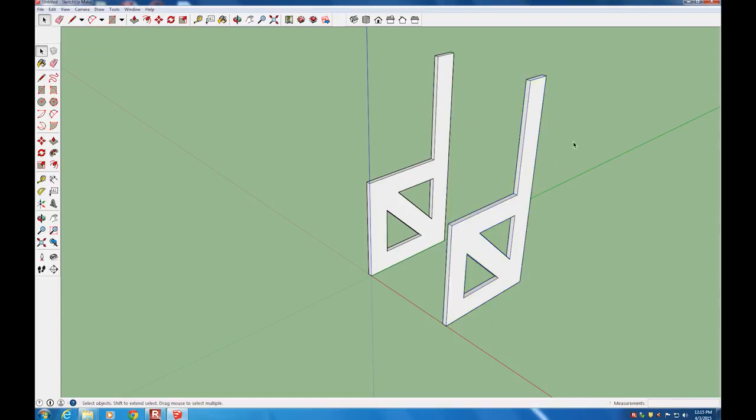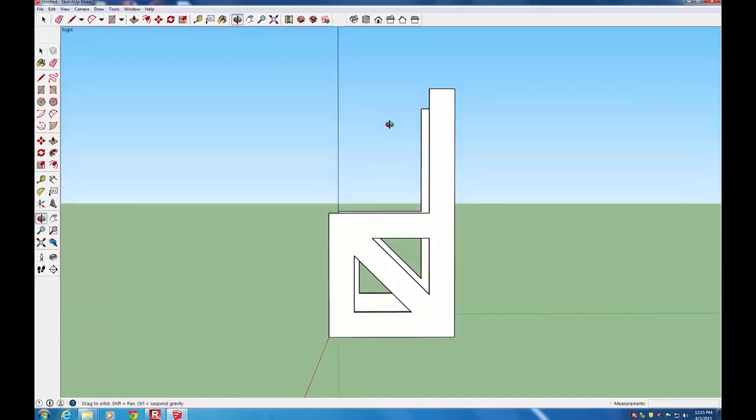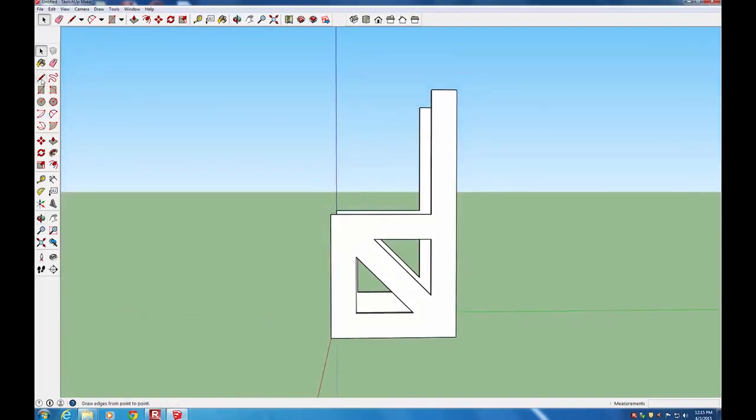So next, we're going to add some guidelines to the side of the chair to add the cross braces. So I'm going to switch to the right view so we can see the side nicely, and then start drawing these guidelines. So there's a lot of little lines here. The dimensions are in the handout, but I'm going to go over here, 0.025 meters, and then down 0.1 meters.